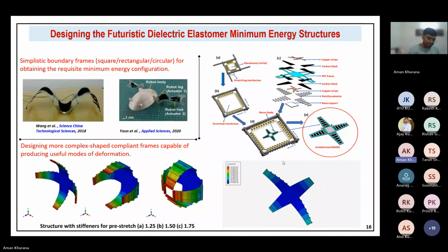So there is definitely a challenge. One way, you can go for the silicone elastomer; it will not have a significant viscoelastic effect. The second way, if you are using an acrylic elastomer because it gives very good actuation, you first provide stress relaxation. If you give a stress relaxation of 24 hours, it will have much less viscoelastic effect, and you apply voltage in a very small quantity, like 50 volts, and keep on increasing it. That will mitigate the viscoelastic behavior in this acrylic elastomer. Those are the two ways to overcome this issue. I hope you understand, or I am making sense.